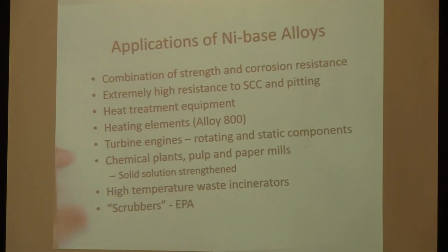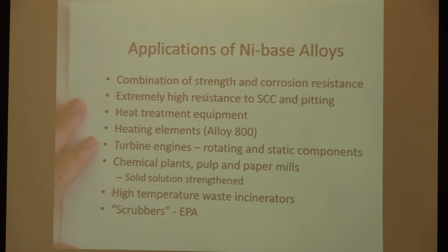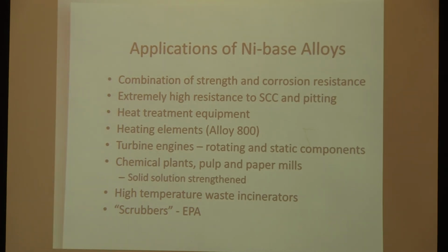Just spend a few minutes on applications of nickel-based alloys. The main reasons or applications for nickel-based alloys have to do with they have a great combination of strength and corrosion resistance, often at high temperatures. And they also are extremely highly resistant to stress corrosion cracking and pitting.